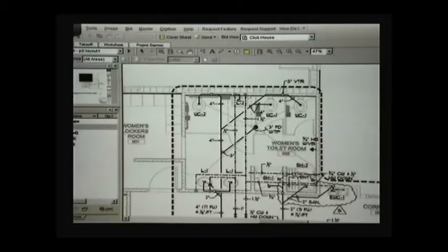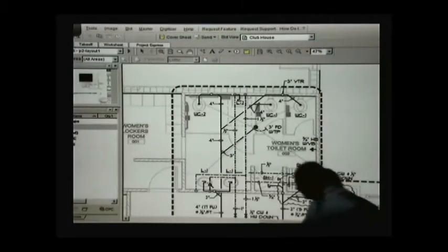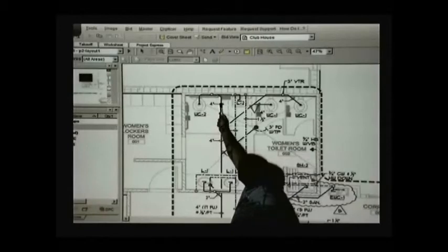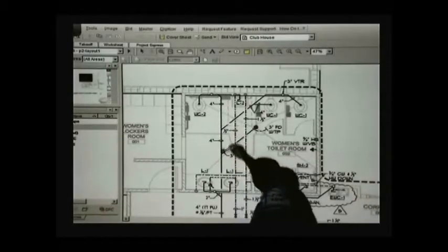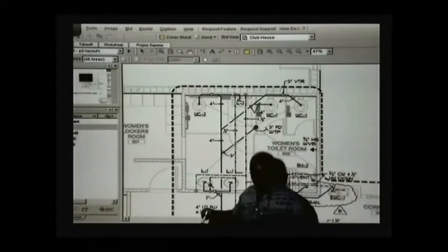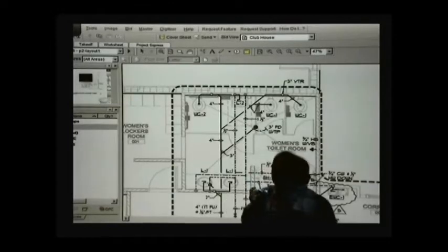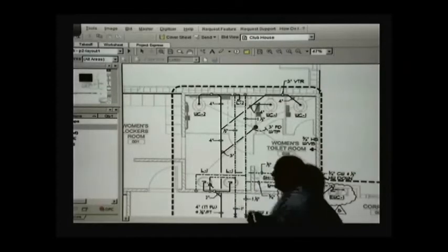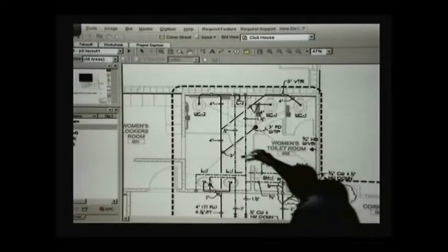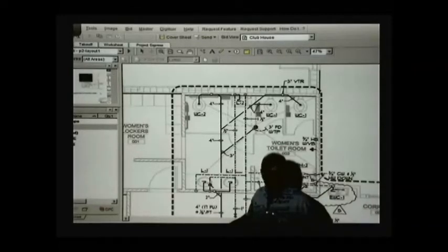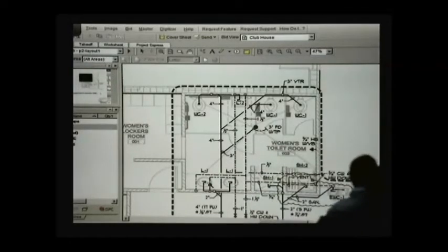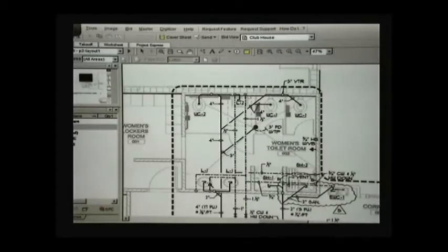Additionally, we have also the problem that when you come out of a water closet, for example, that water is going to move by gravity, right? So if your pipe is horizontal, where do you think that water is going? Nowhere, right? So you need to have certain inclination for the gravity to pull that water down. But when you see the drawing from the top, you can't really see the inclination, right? So you need to include in the software this slope,